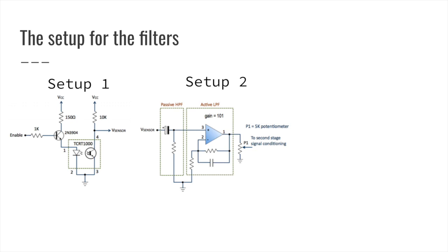Once the filters are added, the circuit is filtered, and we need to amplify the signal once more with another round of passive high-pass filters and active low-pass filtering. We use the same resistors and capacitors as before, using the one remaining resistor for the LED, 1 kΩ, giving a total gain of 101 times 101, that is 10,201.